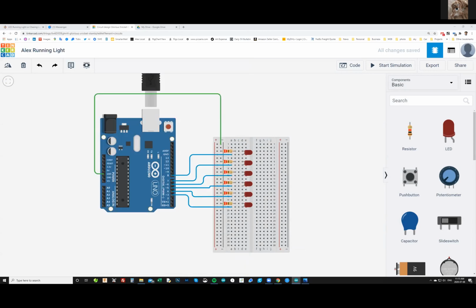My light doesn't turn on when it goes on 8. It shouldn't turn on yet because we didn't program anything, right? Probably plugged it into the wrong leg. Oh, yeah, right. We haven't yet programmed any code to go through the pin state. So it's always a two-step process. One, you need to make sure you build it on your board: 5, 4, 3. And two, you need to make sure your code is actually sending the right signals to the pins where you connected. One cable short.